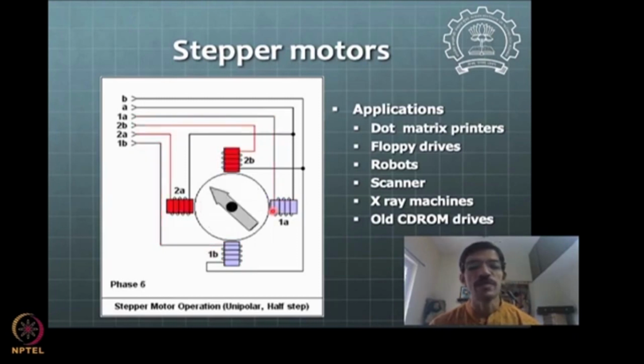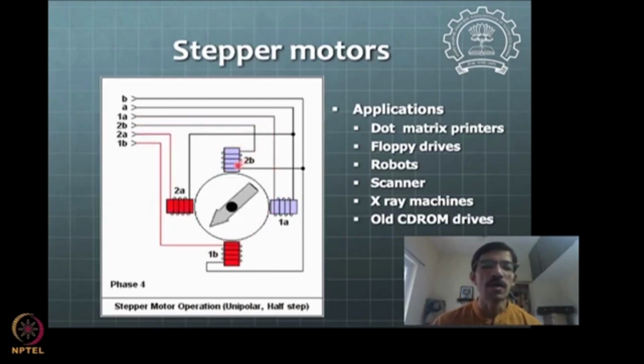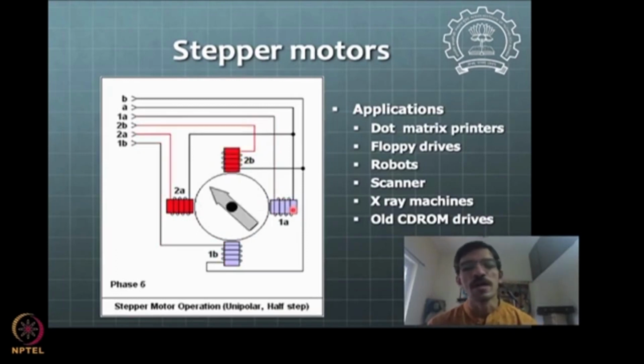It's a very interesting way you can see that we can operate stepper motors to give really high resolution, although the motor is designed to give only a single step or half step or something. By changing the control, or by changing the amount of energization of one coil versus the other coil, one can have many different possibilities. Okay, so we'll look at those possibilities again in the future when we deal with more details about actuators.